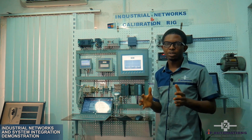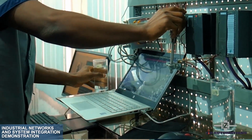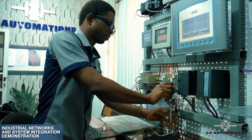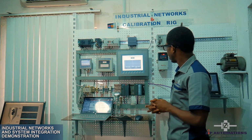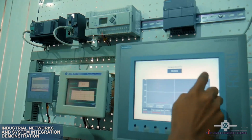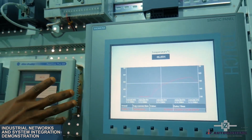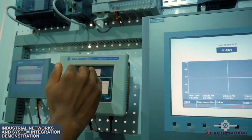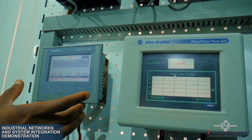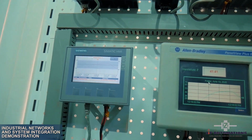So what I'm going to do right now is I'll remove the transmitter from hot water and place it in cold water. And you can begin to see that the temperature is going to start dropping rapidly. You can look at the graph here, it's trending downwards. On our panel view HMI, you can see that it is also trending downwards. The temperature is reducing. On the KTP400 connected to the Schneider, you can see that the temperature is also reducing.